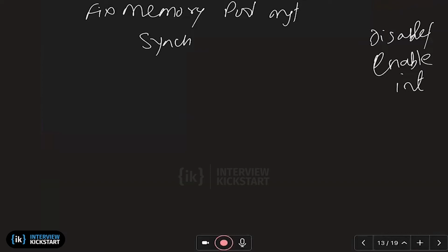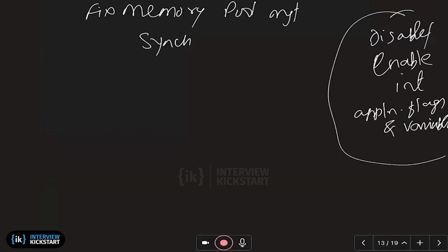And then you implement all the synchronization using application variables, flags, and so on. So basically, it's putting a lot of load on the application developer to think about these things. Those things, which are very typical in embedded systems, have been taken care of by the RTOS primitives. So what is typically required across applications is already available in an RTOS. That is the advantage of an RTOS, right?